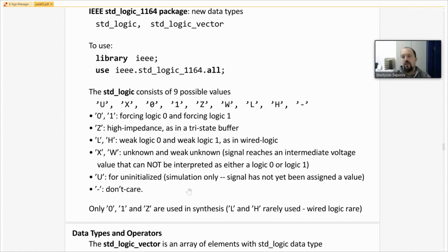So how do you understand the high impedance state? This means that we have certain high resistance on the output of our pin, if we're talking about a microcontroller or FPGA pin directly connected to the circuit. If 0 or 1 is an output, it's employed to manipulate circuits somehow, to change the parameters of a circuit, to perform certain work. And if we're talking about Z, this means that we don't want to change any parameters.